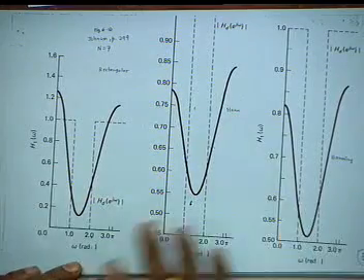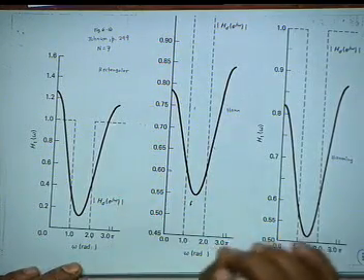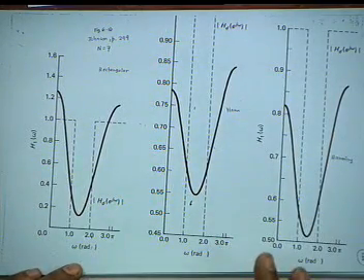Why did that occur? Because of the property of the analog filter from which we derived that filter. Geometric symmetry was continued in the digital filter also, of a special kind. It is not the ordinary geometric symmetry, but here you have no control, there is no parameter to control the symmetry.